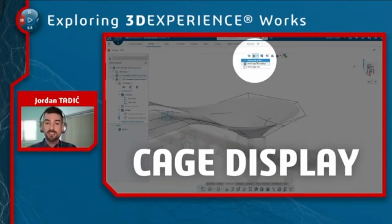Essentially, remember with that style spline, it's always best fitting a nice curvature continuous spline in between those cage points. Unless I crease this corner that's going through here, it's going to be a smooth transition, and that's what it's doing. It's just rounding it off.